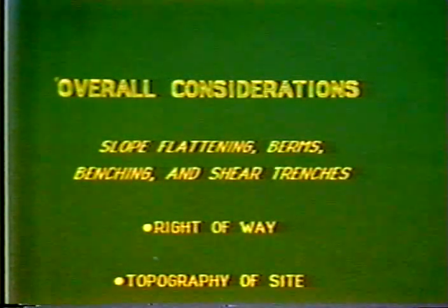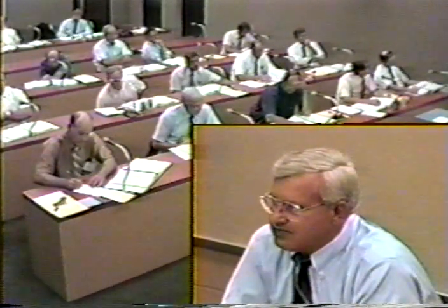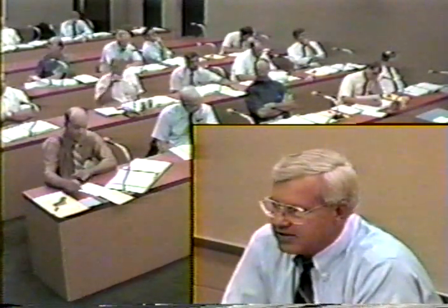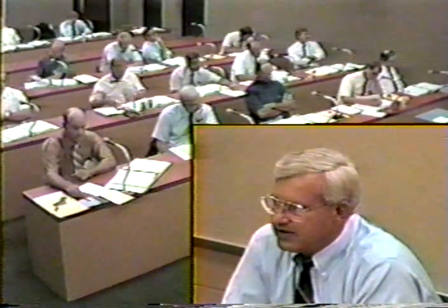Can you move heavy equipment to the toe to do the work? Do you have access? Here again, the inventory system would be very valuable, I think, that if you've got a section of highway that looks like it could fail, sort of think out these things. Think out, how am I going to get equipment to the toe if I've used slope flattening or a berm or some technique? How am I going to do this? And you could put this in your notes where you've inventoried a particular section. Just a place where it might be difficult to get down to the toe of the slide, so you need to take a look at that.